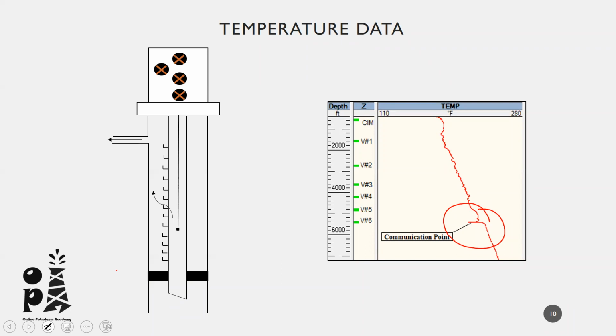So you saved around $2 million, the cost of a rig workover, and also saved much time and cost of changing many valves blindly without any reference log. So running with PLT helped you to quickly and exactly identify your leak points, run and change it, and resolve your well.